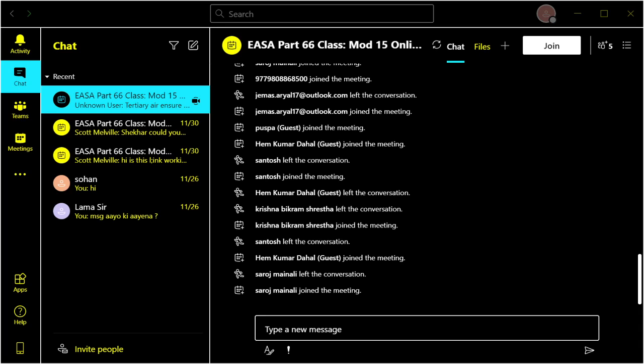Thrust bearings only carry axial loads. So just think through the axis of the engine. It's not to do with centrifugal force, although they are spinning. It is purely the thrust, through the axis of the engine. Normally used in conjunction with a roller bearing or a radial ball bearing. So axial load only. When you're revising your bearings, make sure you understand that there's usually 2 or 3 questions, or at least 2 questions on bearings. Make sure you know which one is which, but we'll recap these as we do revision.